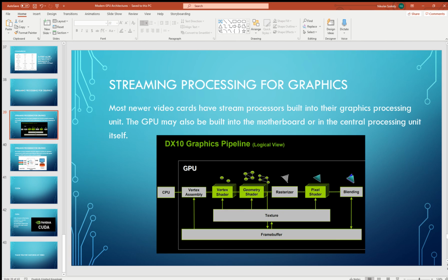Stream processors are well suited for traditional GPU-focused tasks such as image, video, and signal processing. It's becoming increasingly common to utilize the stream processors on the GPU for both general purpose and scientific number crunching. Stream processing techniques work well for ray tracing, computational fluid dynamics, and weather modeling. Applications require massive vector operations and high throughput computations.